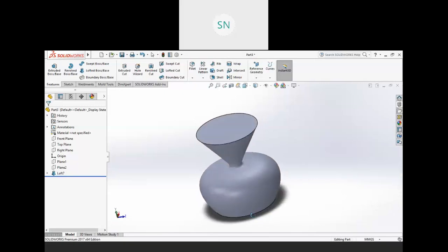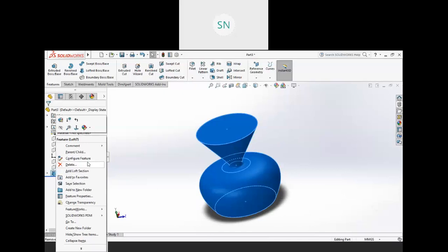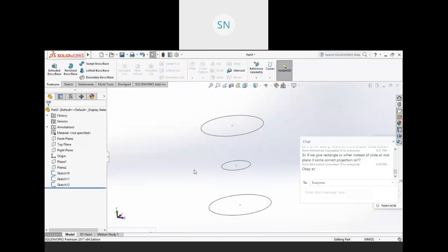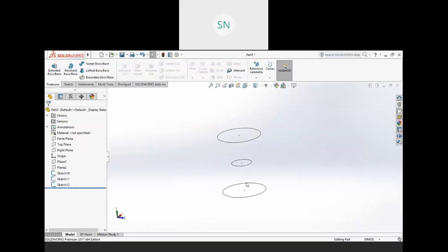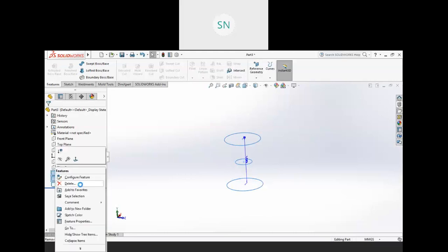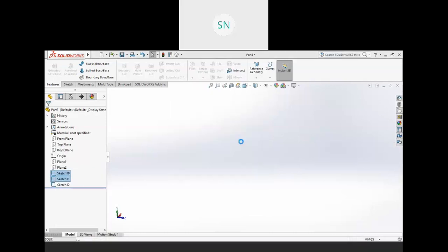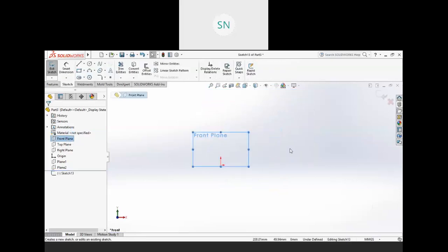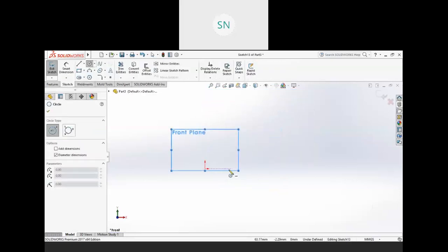So this is start and end constraint. Now the next option we have is close loft. Close loft is actually going to connect your loft profile. So for example, let's create something new for that. So delete this thing. Now on the front plane, I'm creating one sketch, circle.